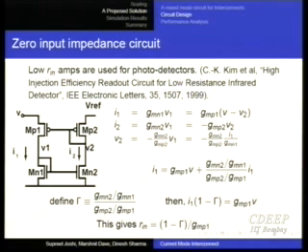What do we physically, this is all textbook stuff. Negative input impedance. What does negative input impedance mean? Yeah. So as I change the voltage, as the voltage decreases, the current actually increases. Right? And because of that feedback, the voltage feedback that I have.